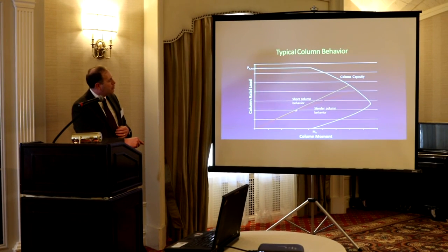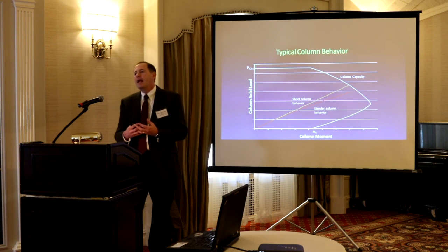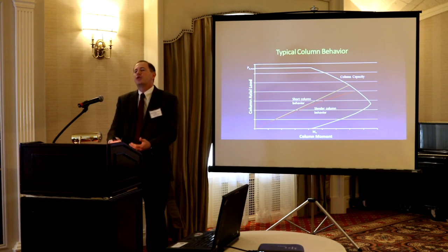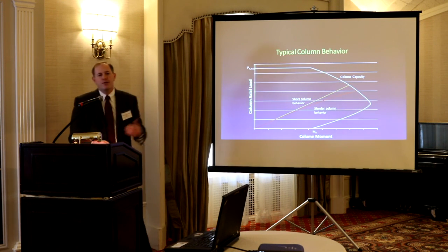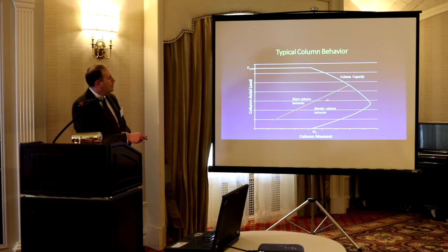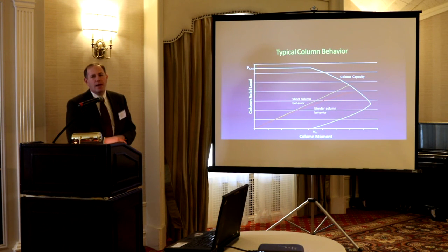As I continue to increase the load, because of the bending, it is second order effects, and it produces more moment than what I have for the same load. So if I'm at this load level, I actually have an increased amount of moment I need to resist.